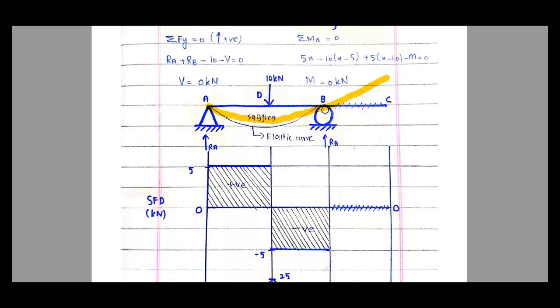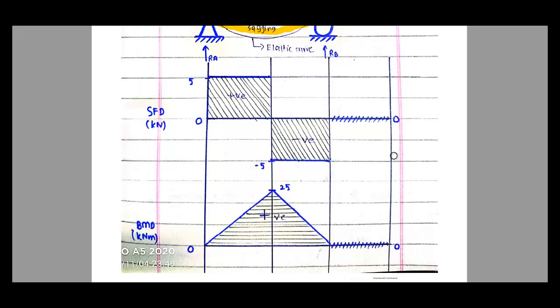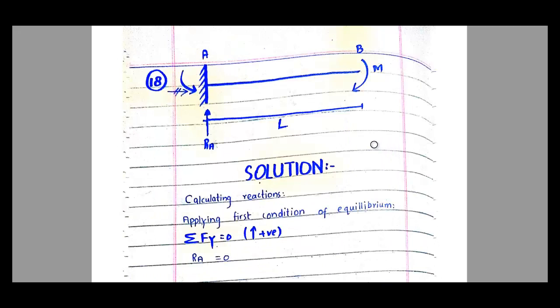We have not discussed internal hinges yet. So in any problem that we have solved till this point, there will never be a sharp bend in the elastic curve. So the same elastic curve will just continue up to point C. And the rest of the solution seems okay.